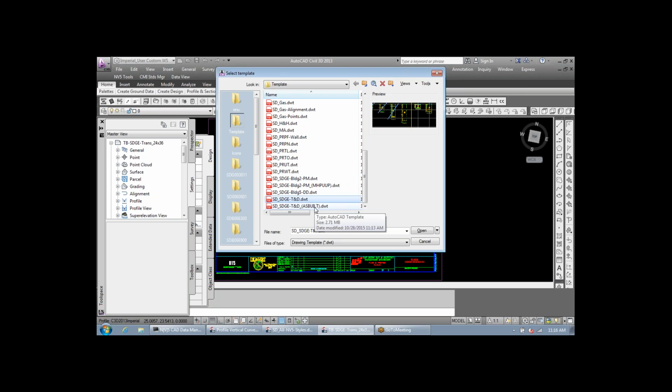So if you do get into as-builts for your transmission and distribution, be sure to talk to me and we can address that workflow in particular. I've done quite a bit in terms of projecting those points onto the profile to make drawing your profiled as-built trench a lot easier for you. And there's some tricks to that. So I want to be sure to pass those on as needed. Projecting points to your profile, when you start talking thousands of points, you can experience a lot of hang-ups, and there's some tricks to getting that to work.